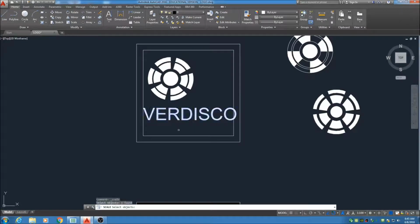Now, another way to do it, let me do Control Z to get back where we were. Scale tool, select it, space bar, select your base point. Another way to go is you can manually type in what you want. Anything below the number 1, for example, 0.5, is going to reduce the size of your object. 0.5 would be a 50% reduction. Anything above the number 1 is going to make your object larger. So 1.5 would give you a 50% increase in size. So what I'm going to do is I want to shrink this down slightly. So I'm going to do 0.95, enter, and I look at it and I say, am I happy? And then I say, yes, I am happy, so I leave it there.